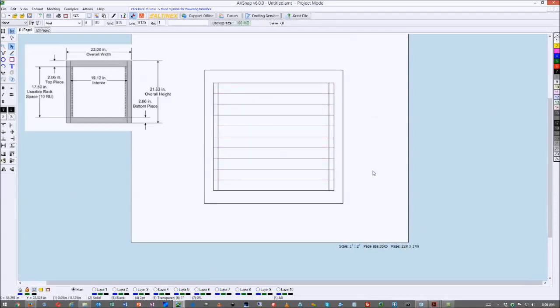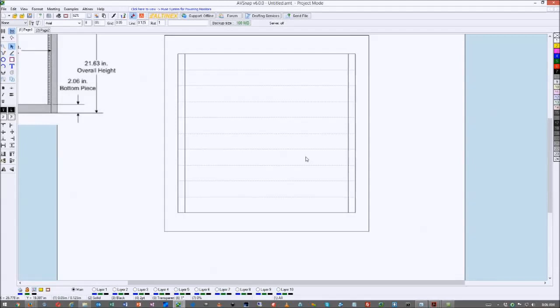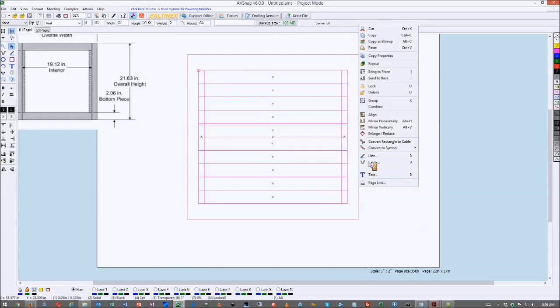So now you have your pretty much rack elevation done. You have the rack set up. So one of the things people do sometimes, they make it a little dot lines like this. So you have a dot line so you can see how everything lined up. So the next thing we need to do is to select all of this, right click, and convert it to symbol. And this would be an outline symbol.